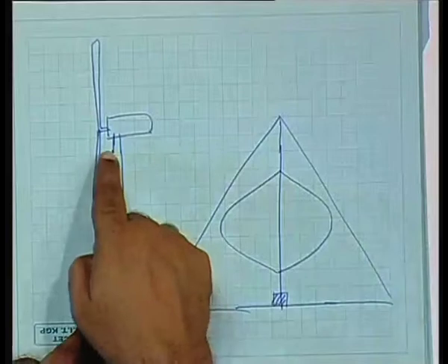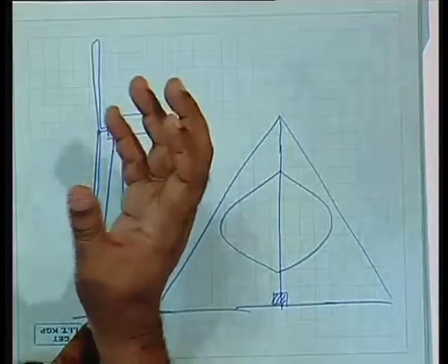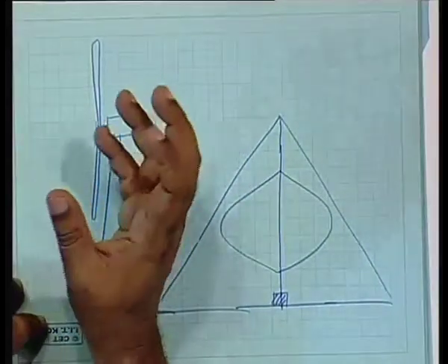Notice that the horizontal axis wind turbine has to be oriented in the direction of the wind, while the vertical axis wind turbine, it does not matter. So another complication and another control system can be avoided in case of the vertical axis wind turbine. This control, the controlling to face the wind, is called yaw control.